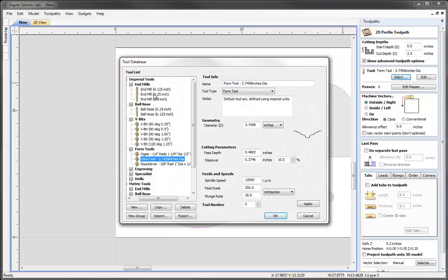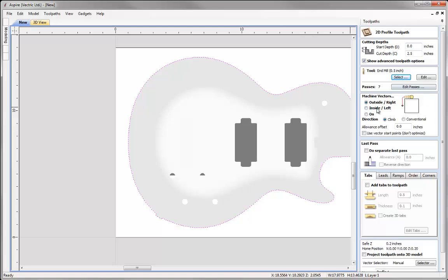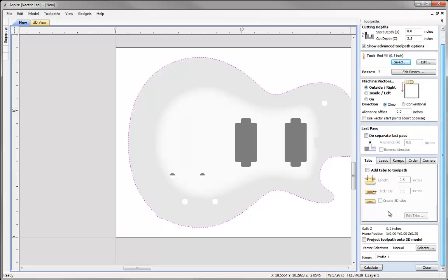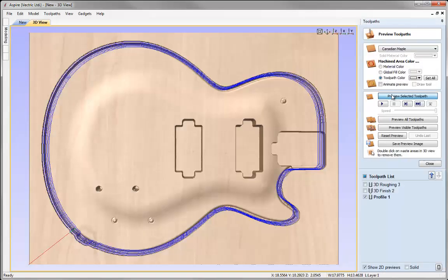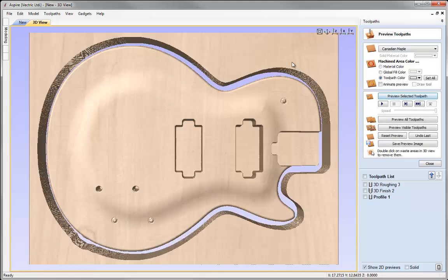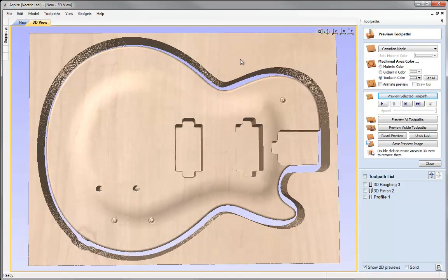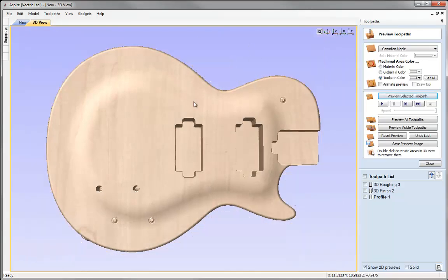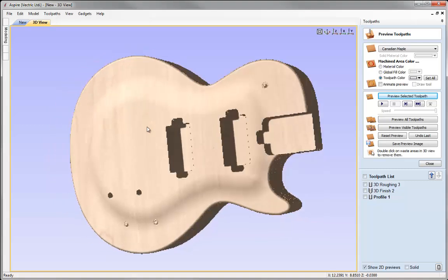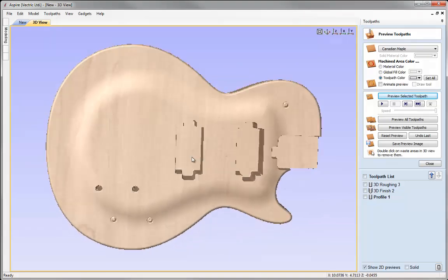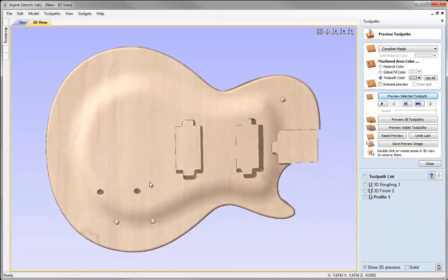Use a large end mill tool, so I'm going to use a 1/2 inch end mill there. I'm going to go around the outside and I'm going to calculate that toolpath and then run the toolpath. And then if we double click the excess material on here, which would be this area here, that will then get rid of that material for us. So we can actually then inspect our preview. It all looks good, apart from the fact that we've got the holes that are unfinished.